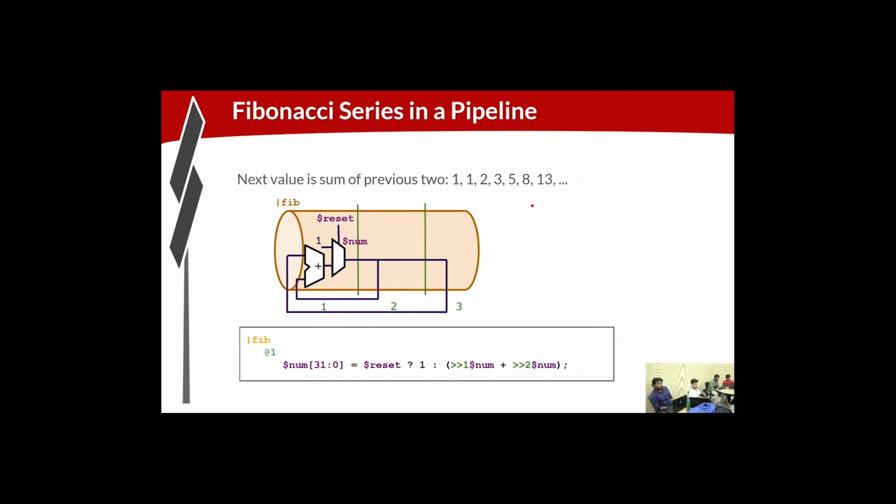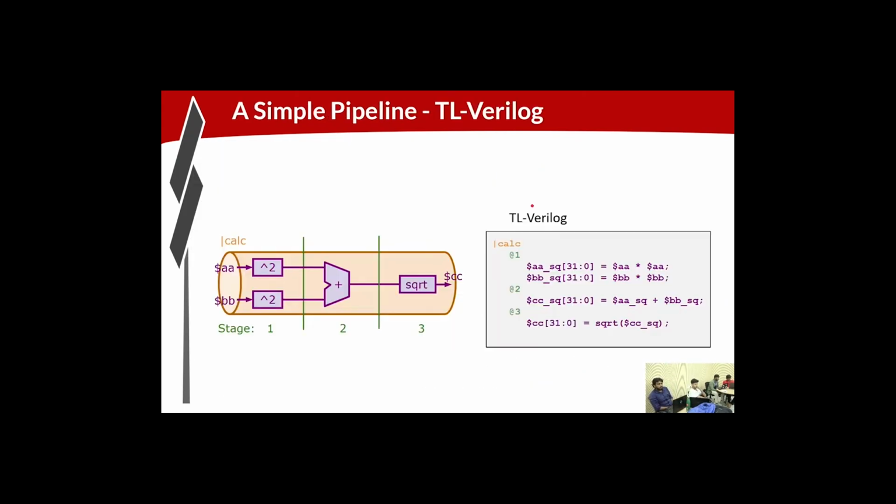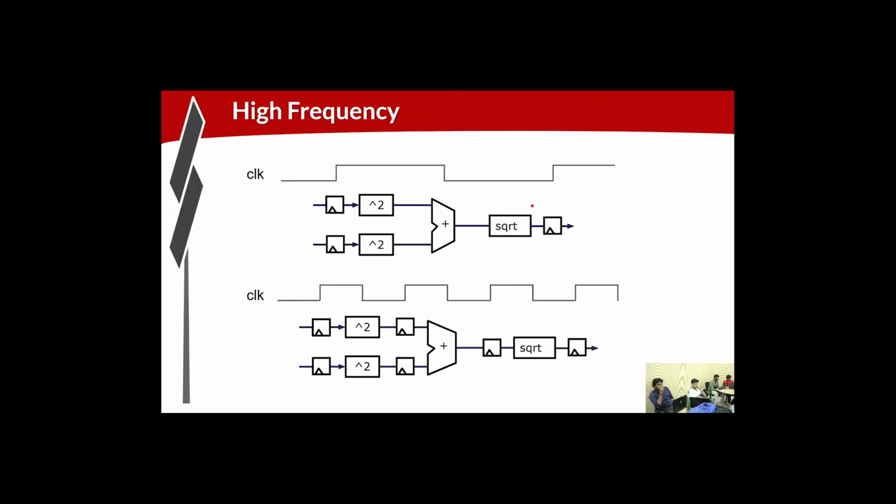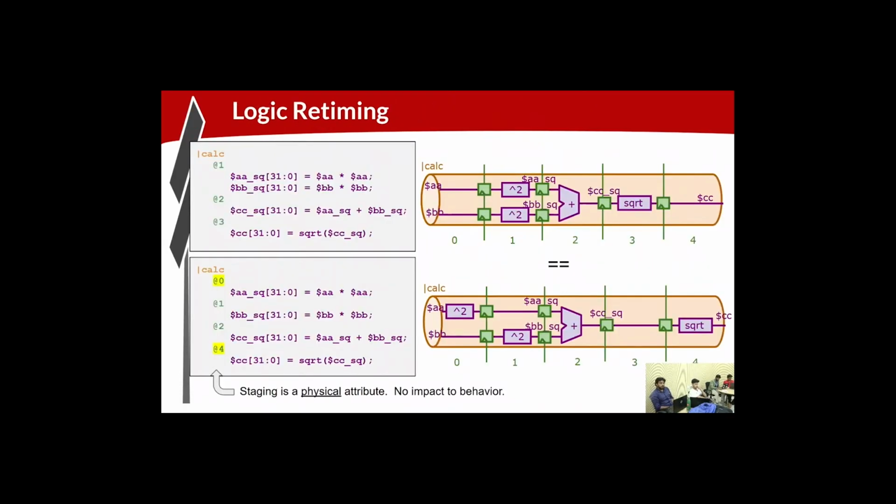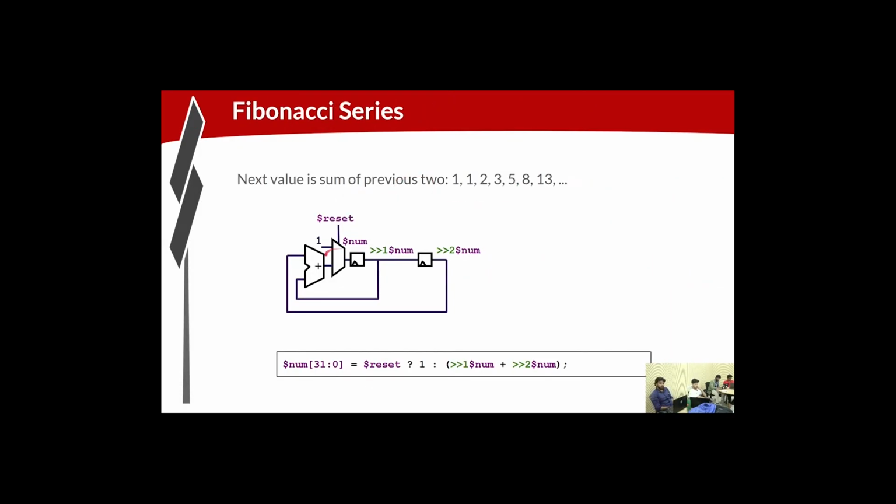I think that's what we did earlier with Pythagoras' theorem, right? We started with a one-stage implementation, and then we stretched it out over multiple stages. So that's the point: once you give yourself the context explicitly of a pipeline, you can very easily take this mux and push it through a flip-flop, retime it through the flip-flop, and know that you haven't broken the functionality.